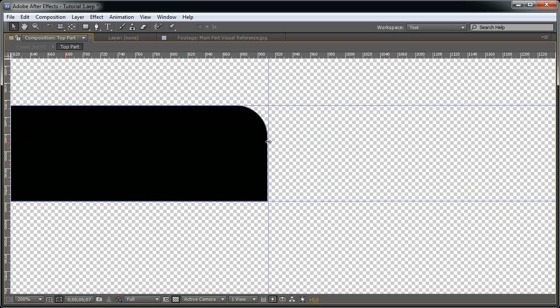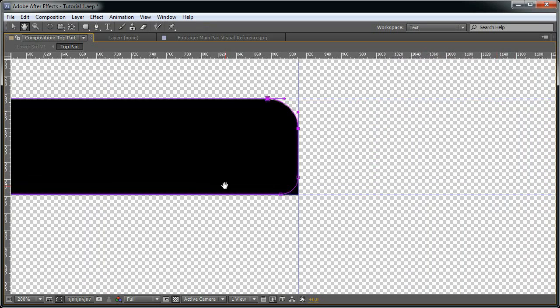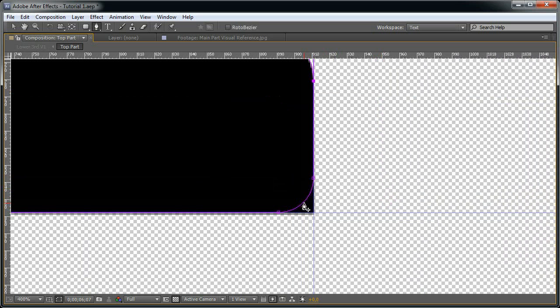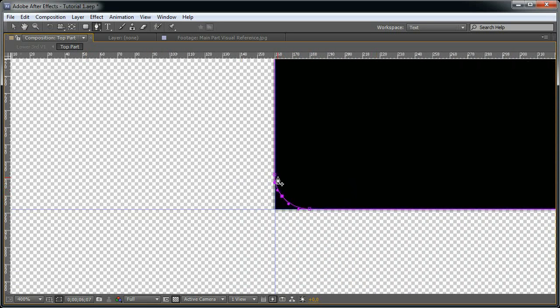the shape, and this will be a bit time consuming because when we create the shape we are going to adjust this corner. But now we have to set a point here, delete this and this point, and just alt click to make it a straight corner, and because of the guides it will snap right into place.